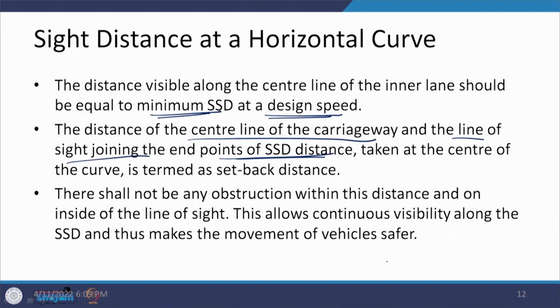With respect to that, if you take the endpoints of that distance of SSD and a line of sight is drawn, then the distance of that with respect to the center line of the carriageway is defined as the setback distance, already defined in the previous slide.